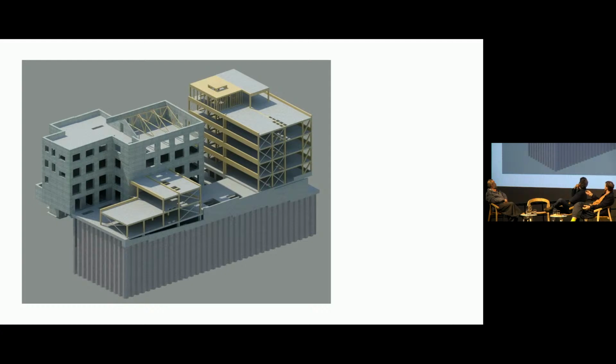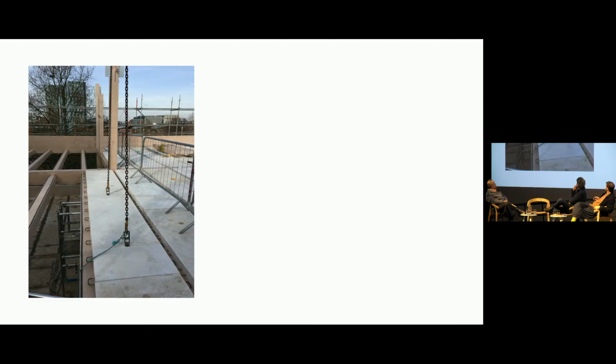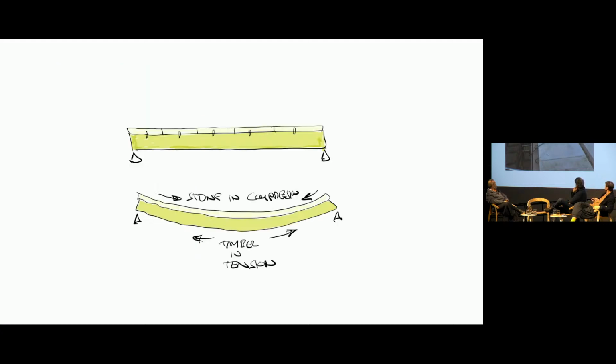So this is a building for the Anna Freud Foundation. All of the above ground structures are a hybrid concrete and timber frame. So we're using LVL Baubuche beams connected to thin concrete slabs, compositely connected. So when the wooden beams flex, they compress the concrete. So the concrete makes the wooden beam stronger. And we built that building without any air conditioning. So it works like this.